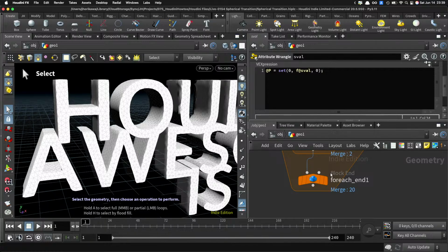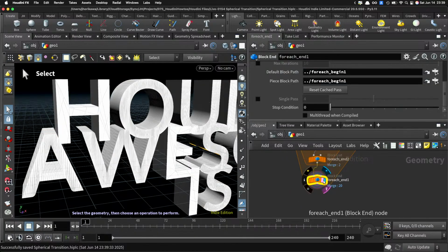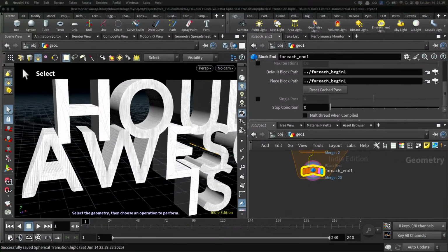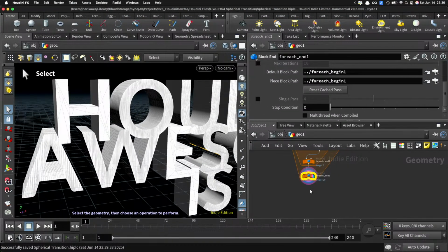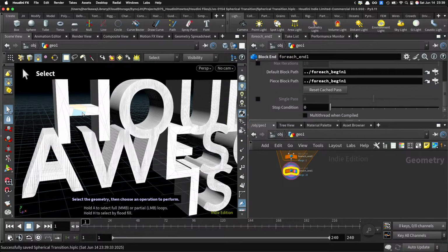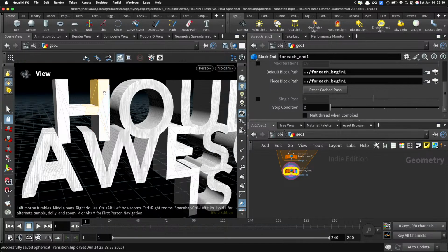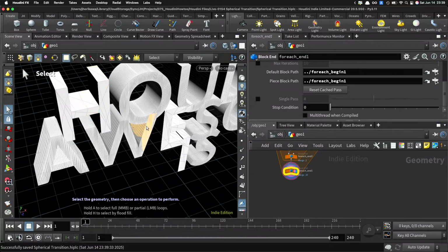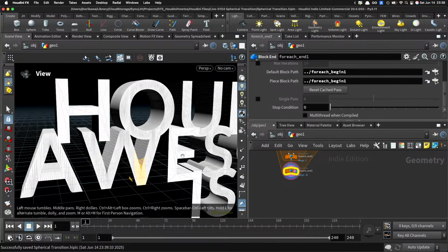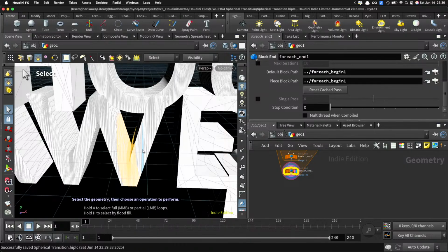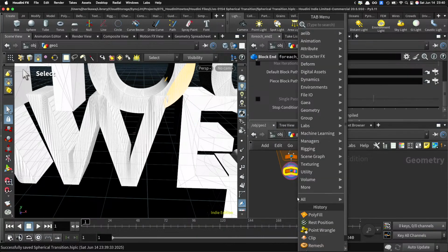Okay, so let's rotate the geometry. In order to rotate the geometry, first things first, I am going to check if each one of those pieces is being cut correctly. Yeah, looks like it. And I want to have some IDs for each of those connected pieces so that I can later scale these pieces based on the center of each connected geometry for dissolving, for transitioning from one geometry to another.